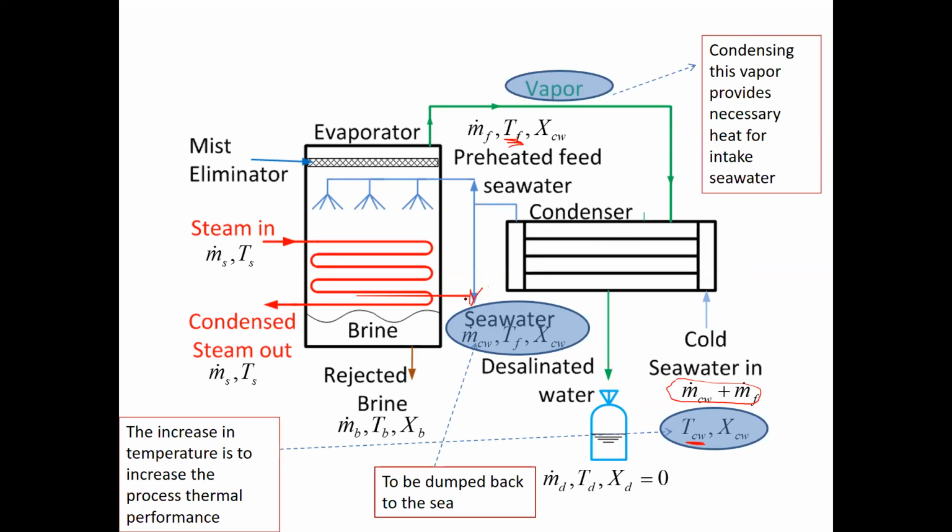This is one problem. The second is you have used steam here to heat the seawater. Part of the seawater will evaporate, but a bigger part is going to be rejected. So you are rejecting seawater here, which is at a higher concentration, but it is at a saturation temperature. So you are losing energy here as well. You are throwing away energy to the surroundings.